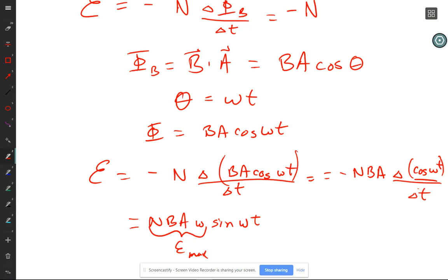Well, then that whole thing is rotating. So the magnetic field is rotating. And then you have coils outside that are stationary. The reason this works a lot better is because now the magnetic field is going to change from north to south with just a tiny rotation of the alternator. So that means you're changing very rapidly the magnetic flux.